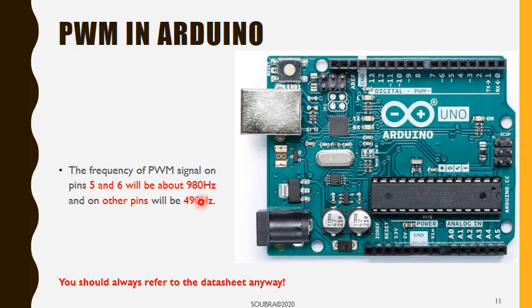So whenever you're going to control a motor and generate the PWM signal, you should check the frequency of the motor, or whether you can have smaller frequencies based on those ones. Always refer to your datasheet, right? And connect them to the proper pin.